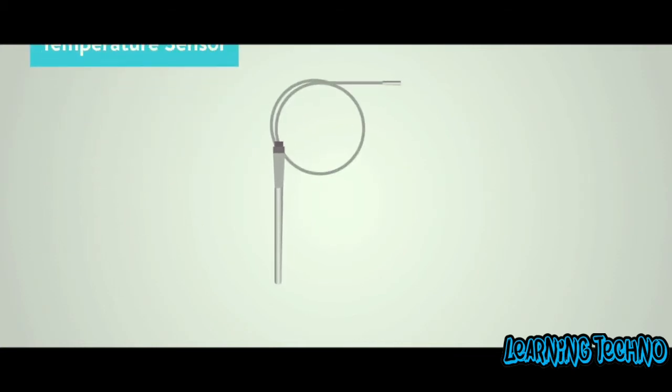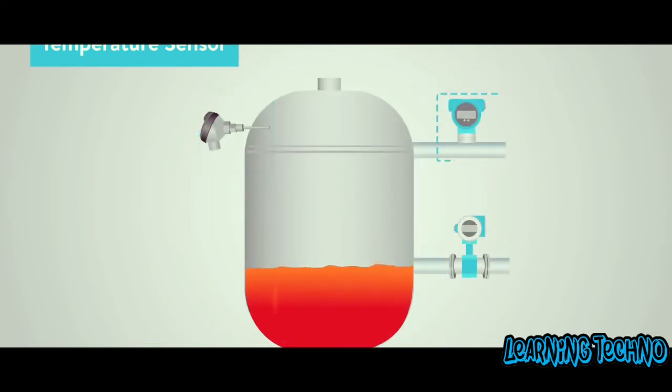Generally, a sensor or transducer is a physical device which is capable of transforming one type of process variable to my favorite signal type. To elaborate on this generalized sentence, let me give you an example. Temperature, pressure, flow, etc. are some process variables, and actually, they are physical characteristics of our real world. With modern technology, and because of tremendous advances in electrical engineering in the past century, we like to transform every measurable process value into an electrical signal.